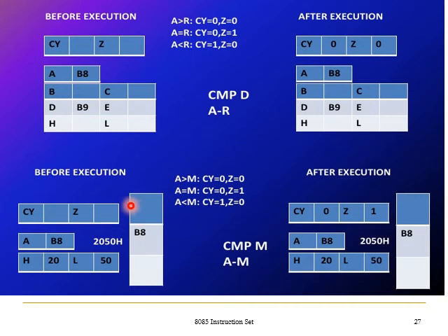If the accumulator value is greater than the register value or memory value, then a carry will occur. At that instant the carry flag will set, so the processor concludes that the accumulator value is greater than the D register or specified register value.